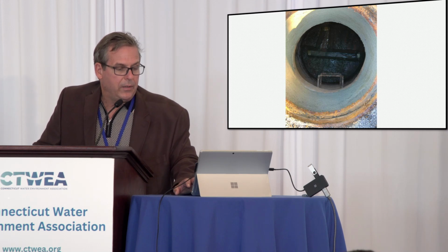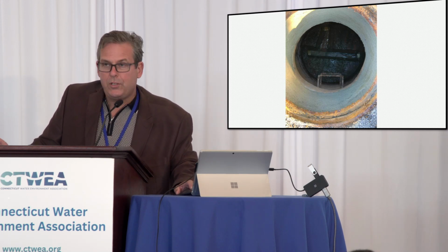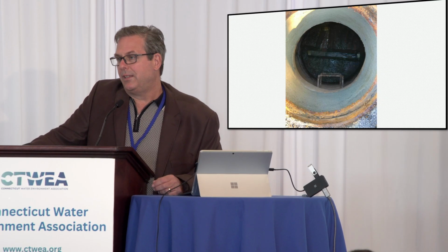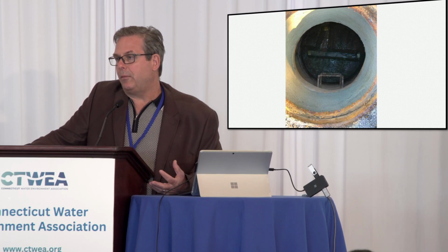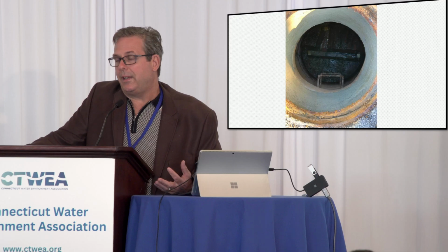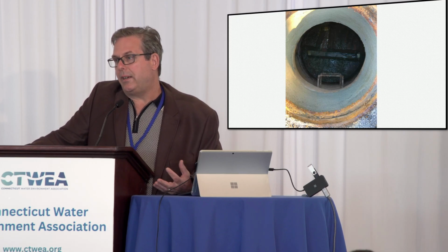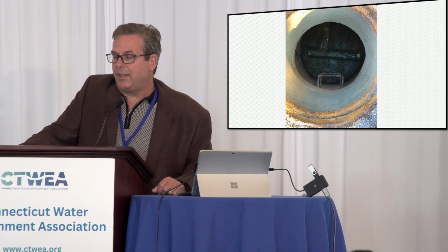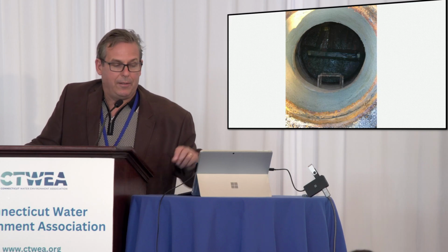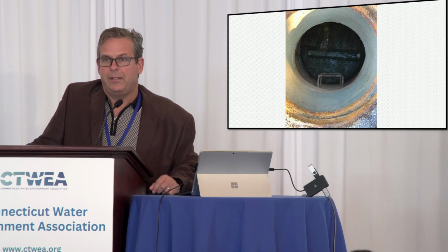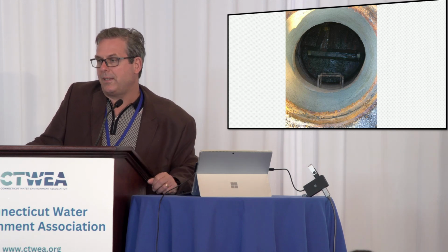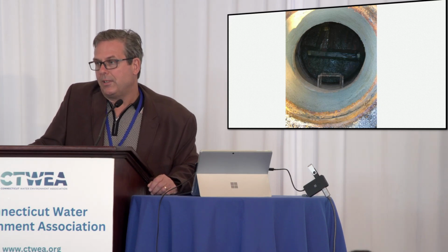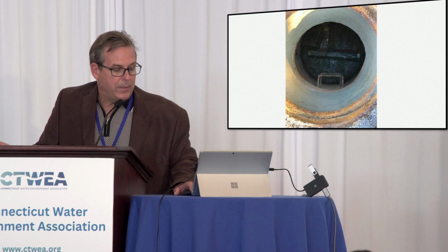One thing, I was at another conference yesterday, and the engineers there, and I'm sure the gentleman from Savvy can talk about this, said that the pH of a brick or the inside of a manhole frame, when you do some sort of treatment, has to be 9 or higher for the product to stick to it. So when I get back, I'm going to get a little pH testing kit, like at ACE, and I just want to test the pH on brick and concrete before we do this treatment, because if it's lower than 9, the treatment won't last as long. That was just something I learned in another presentation yesterday.